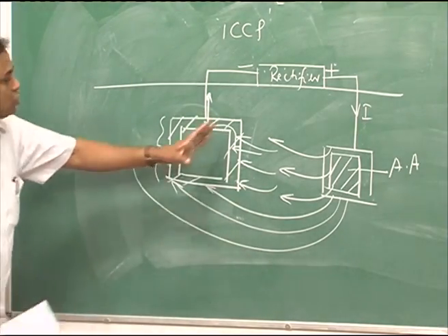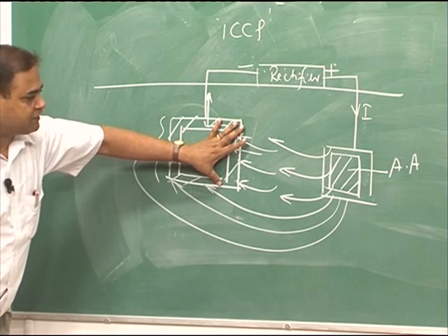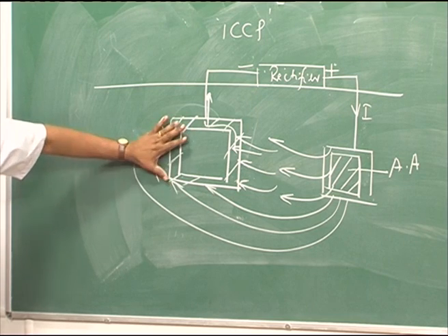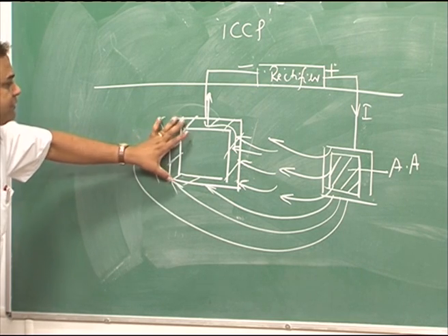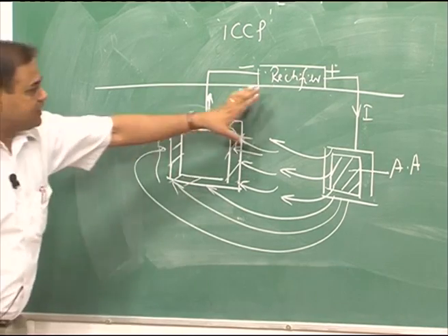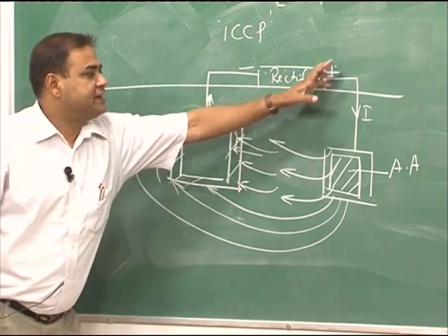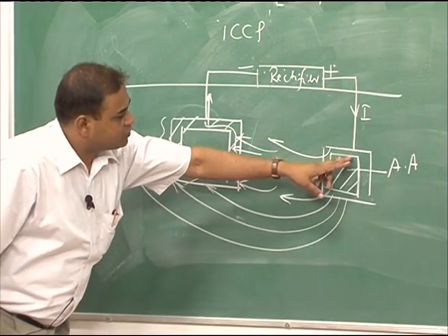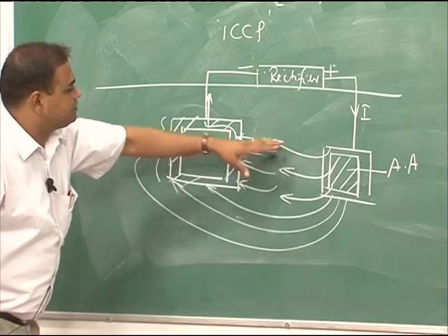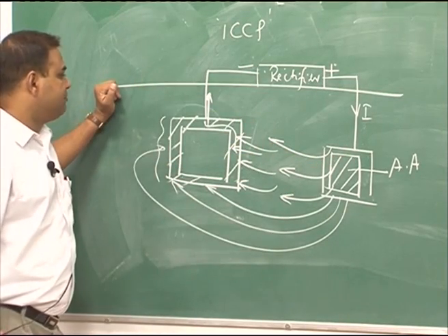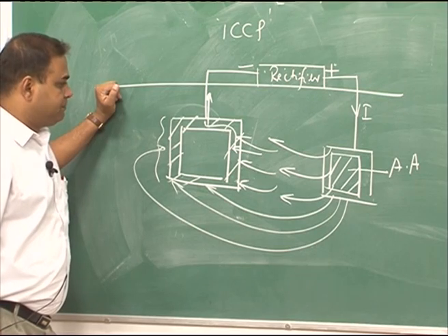So, though we can have protection on the nearby surface, the farther surface will not be protected to that extent. Here the rectifier is sending a uniform, constant current to the anode material, and the current coming out of the anode enters the steel tank.